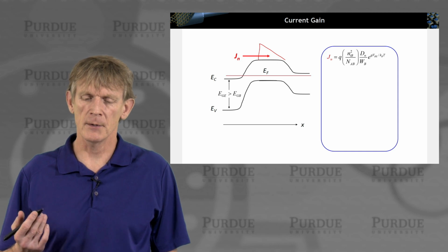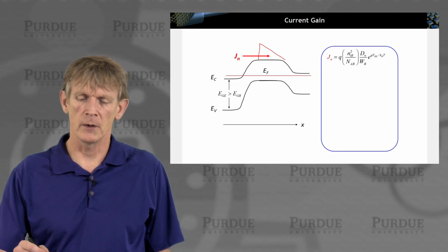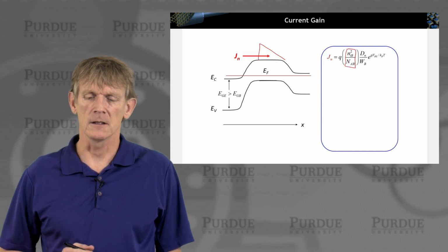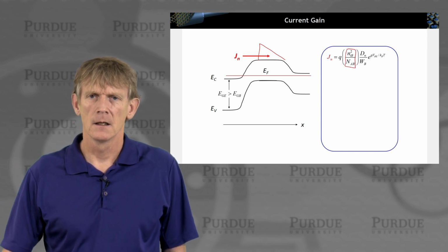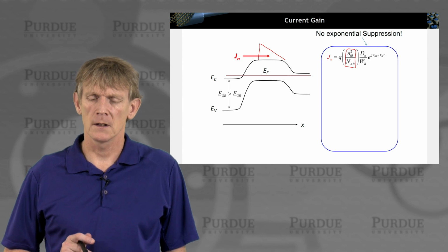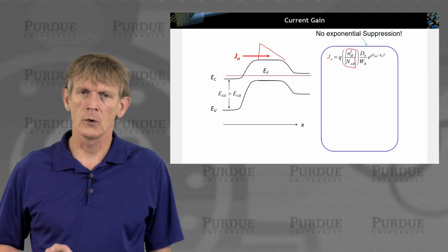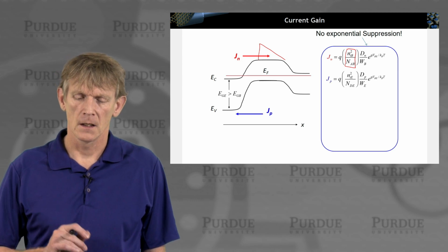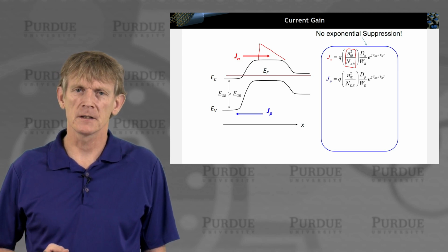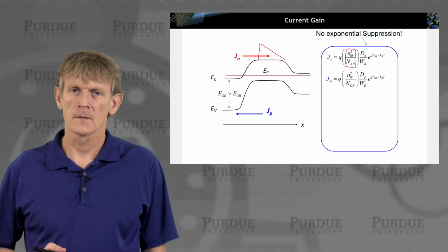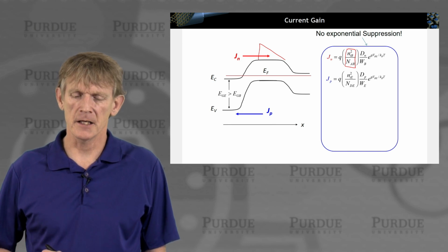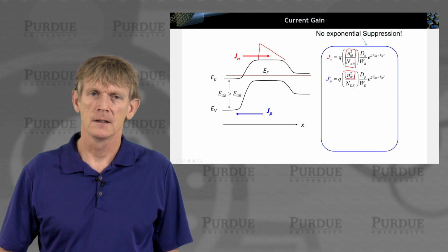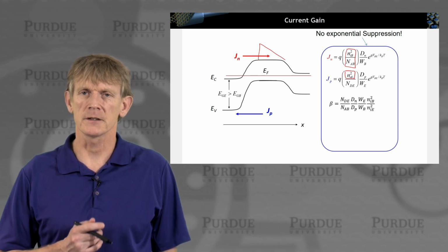Okay, so same expression, but we've modified n_iB here. Okay, so in this expression here, there's no more delta EC that is blocking some current. We have the very same expression again for the holes. Again, nothing changed. The only difference here is that we have now a different n_ie squared in the expression.